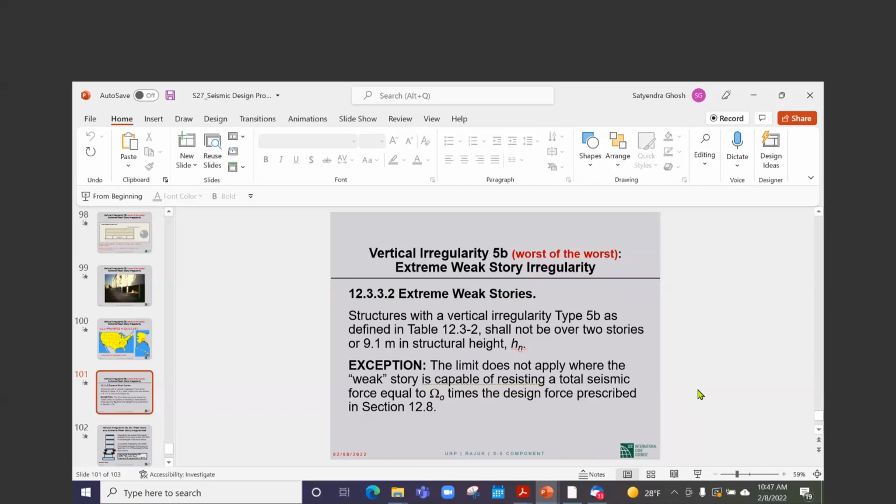So look at that part of BNBC, serviceability load combinations, which we do not have in our codes, and go with that. But again, I would say that in the vast majority of cases it doesn't make any difference, because gravity does not cause drift, unless, and this is a big unless, it's a very unsymmetric building. Then gravity will play a role.